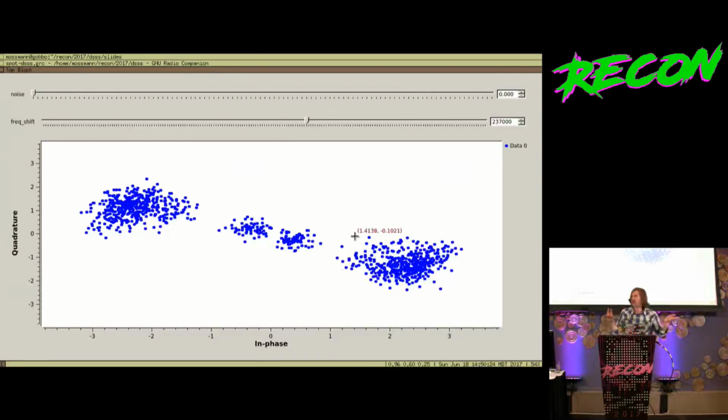The only thing that's sort of complicated about it is that samples are two-dimensional quantities as opposed to one-dimensional. But in BPSK, it's just two opposite points, jumping back and forth. And you'll see some intermediate points near the origin as it's going back and forth, but most of the samples are clustered around one side or the opposite side. Now, if you square a 1, you get a 1. And if you square a -1 on the opposite side, you get a 1. So if you square the signal, these two constellation points collapse together.